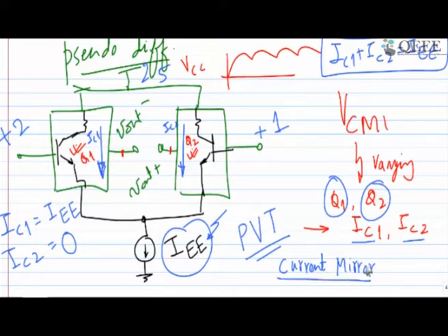This is not part of our course, where we are only teaching the differential amplifier, not the current mirror. So maybe an extension of this can be given to the current mirror, the same topic. If it is coming from a current mirror and they are PVT independent, then IC1 and IC2 depend only on the tail current, which is IE.